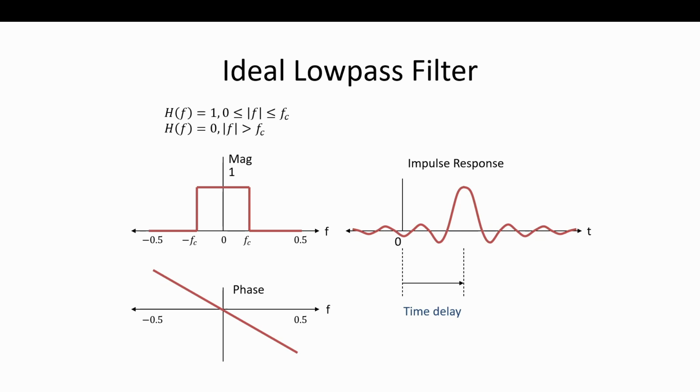If we put that through a fixed, lossless cable, at the other end every one of those frequencies will have gone through the exact same time delay. The phase is different, but the time delay would be the exact same. You're just backing out what I explained earlier. So when you add them all up, you're going to get your original waveform.